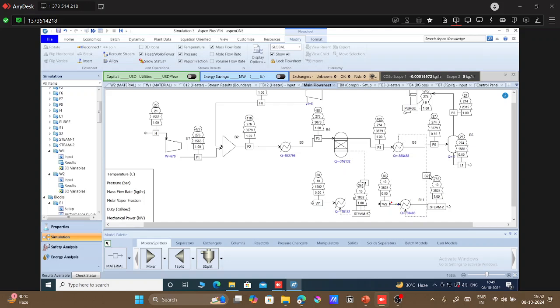In that case, you can understand that there will be a crossover. So the hot steam outlet will be much lower compared to the outlet of the cold steam. So this temperature crossover should not happen. That point also we have to take into account. Right now we are not bothered about that. Right now we mainly want to look at how much steam can be generated.